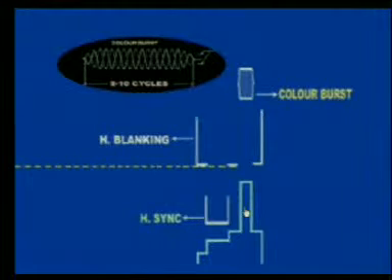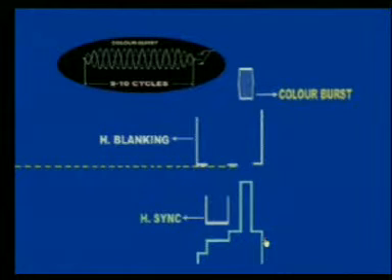It contains the 2.5 microsecond pulse width to knock down the color burst. At the same time, to stabilize the burst gate circuit, it contains the sync pulse duration, which is 4.8 microsecond, and also the blanking pulse duration, which is 12 microsecond. Therefore, this separated sync pulse is now available to lock the horizontal and vertical oscillators.